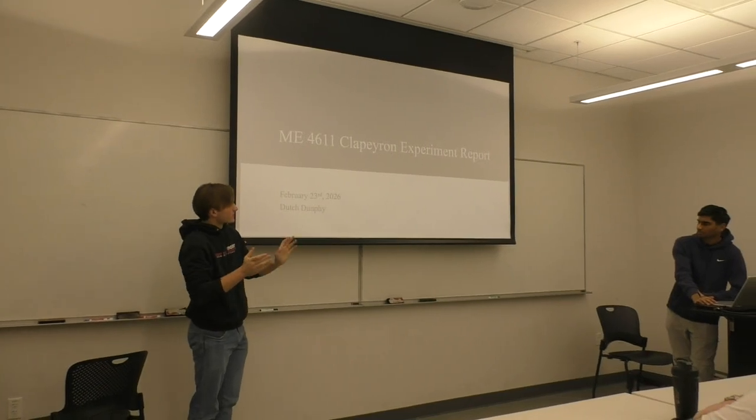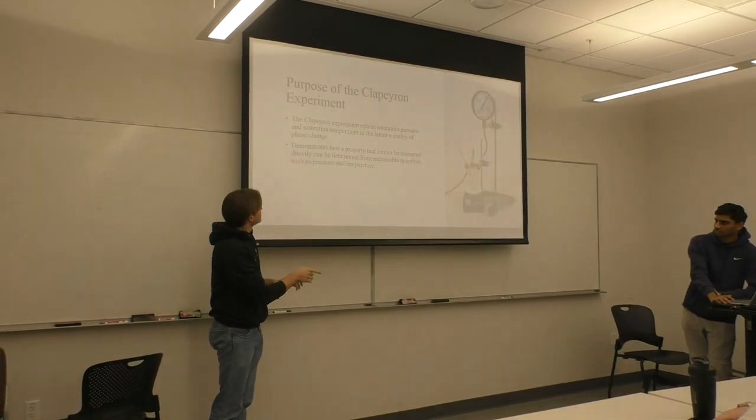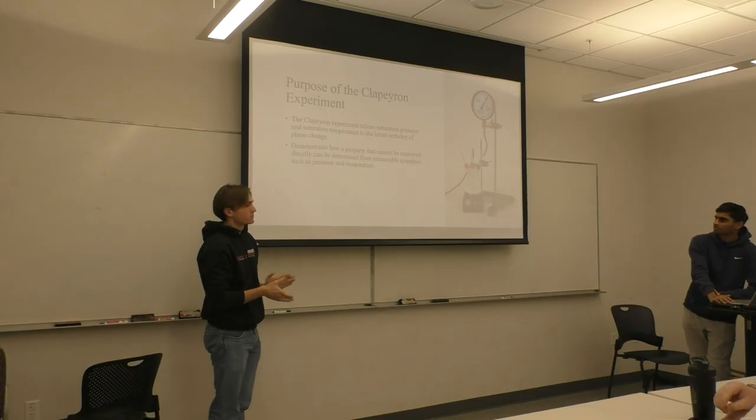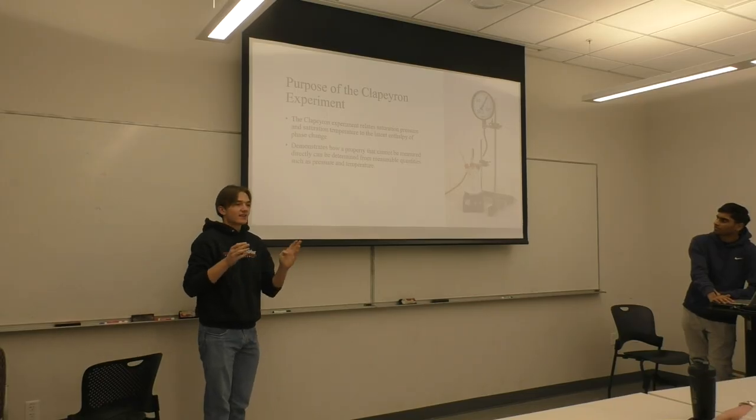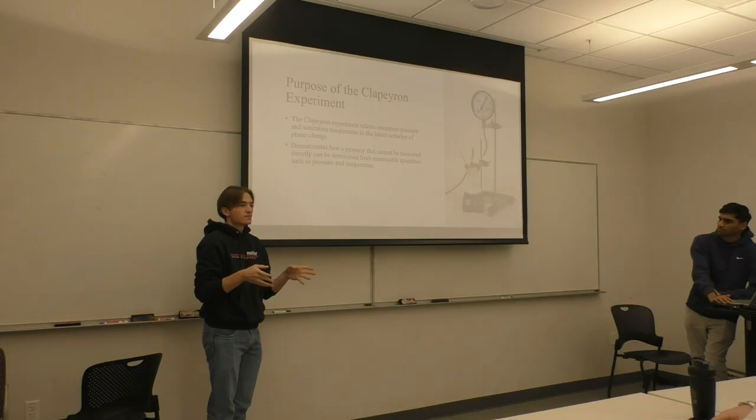I am doing the experimental report for our group. Next slide, please. So the purpose of the Clapeyron experiment is pretty much just to say that a value that can't be directly measured, such as enthalpy, can be measured through stuff like saturation pressures and temperatures.